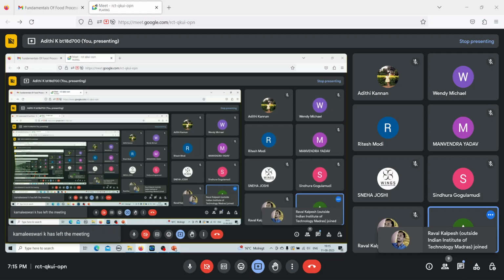If it is very confusing for you guys, you just proceed with this. When to take out delta T out and when not to, just proceed with this. Multiply L into delta T first, always, and then sum at each and every data point, you will get the F naught value.